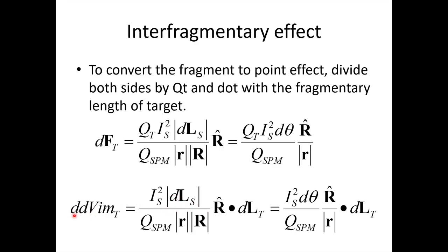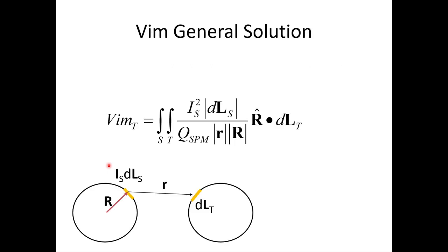And so they need to balance. So in order to compute the complete effect between two wires, you need to integrate over your source wire and integrate the path integral over your target wire. So it's a dual path integral. Again, you don't have to do the full thing. You can do whatever part or section you want to whatever part or section you want. But again, if you want to see the voltage on a voltmeter, you have to go completely around your target loop. And again, that is your EMF. That's the new term for EMF.